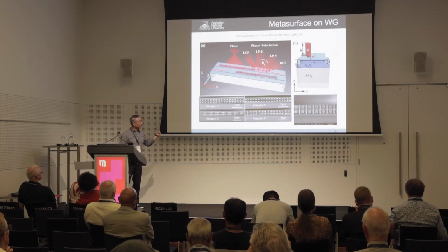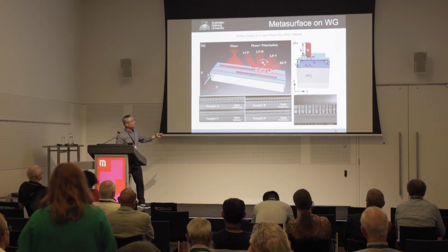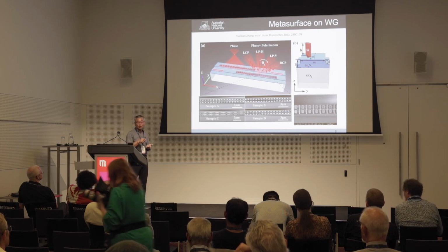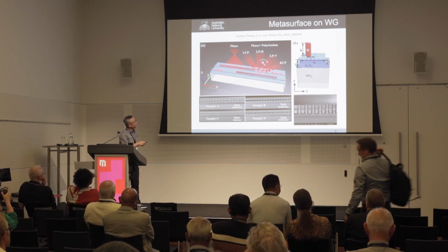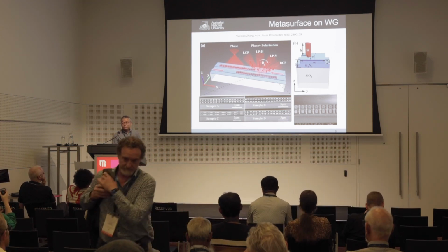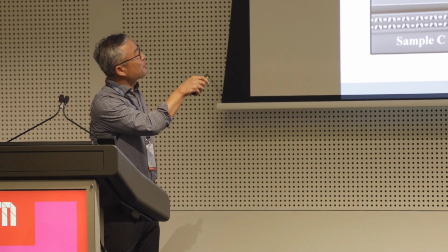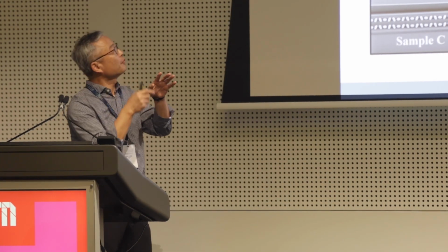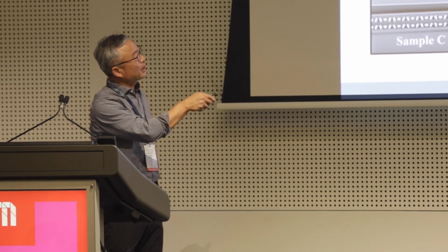The previous example is just putting a metalens on top, but in this project, we want to integrate everything on the waveguide directly. This platform is a silicon nitride waveguide and silicon as the metasurface. By changing the period and the shape of this structure, we can easily make converged or focused light above the waveguide, or different polarizations can be emitted in different directions.